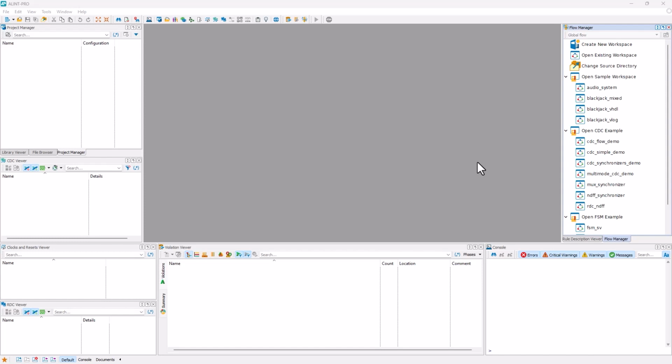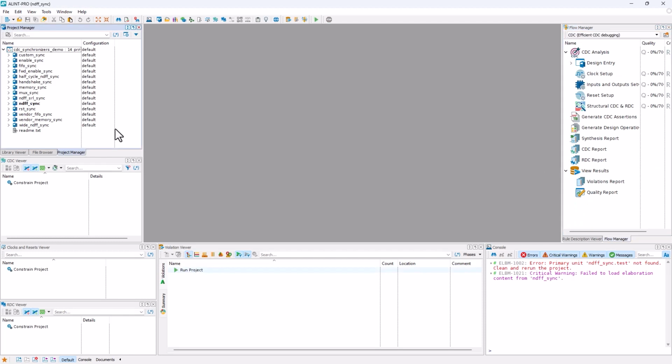In this video, we will discuss a few variations on the simplest kinds of synchronizer circuits that ALINT-PRO supports. Now, for any two asynchronous systems to communicate, you need some sort of synchronization scheme. What we're going to do is head over to the CDC examples, specifically the CDC Synchronizers demo, and we can go ahead and open that up.